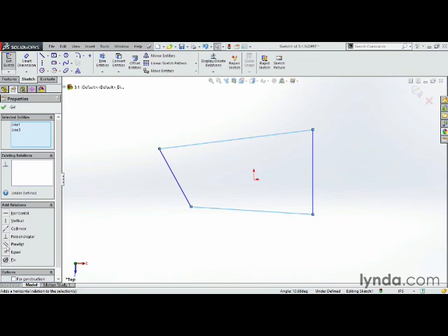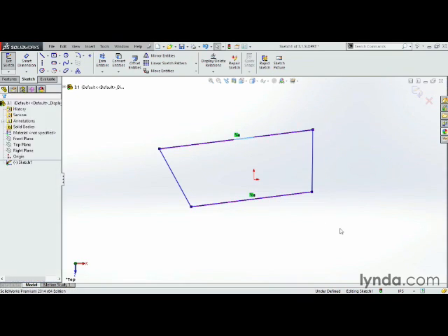So I could say these lines are parallel, and notice what happens. They become parallel, and it gives this little green box showing that these two lines are parallel. And notice if I mouse over either one of those lines or the little box there, it shows the two lines that are involved in that parallel relationship. And notice that little 0 next to each one. The 0 means nothing more than to match a 0 with another 0.